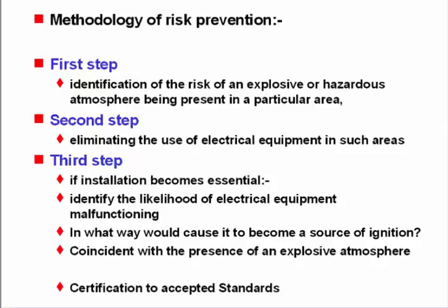Certified equipment you pay a premium for, and you're also going to be maintaining it and keeping records on a regular basis. So if we can get the electrical equipment out of the hazardous area, it's best for the bean counters, sorry, the financial people, and it's also a safer method of working. However, in a lot of situations, we can't eliminate the electrical equipment from the hazardous area. We need that electrical equipment to either control the hazardous area or provide measurements. So if we're stuck with having this electrical equipment in the hazardous area, we need to make sure that that equipment is suitable for that risk.